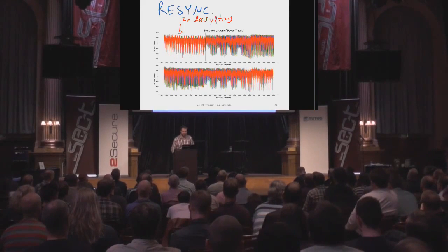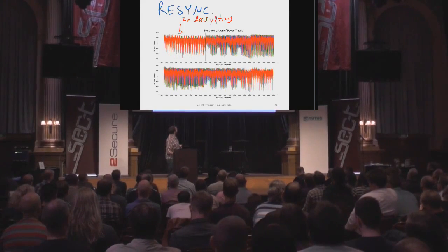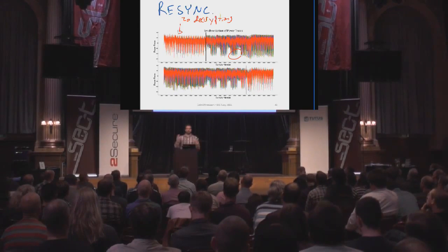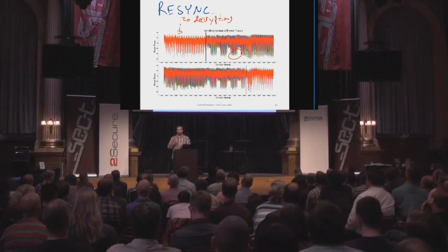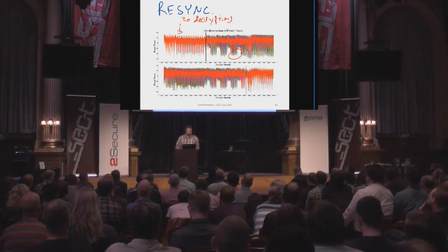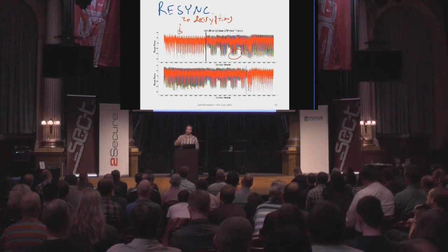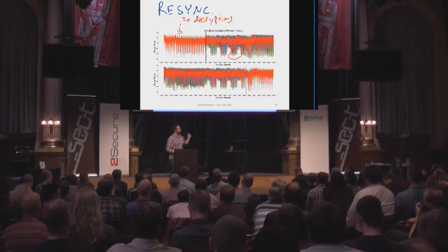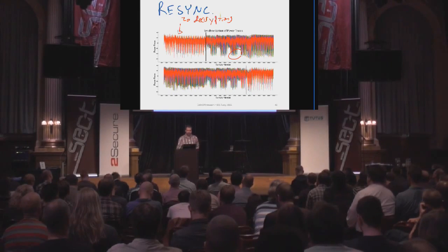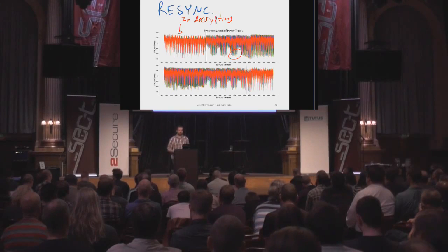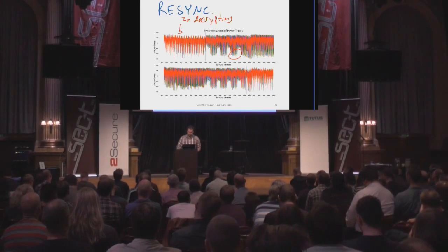What you see is that it looks very nice and aligned. At some point, it looks really messy, so they're no longer lining up. All that happens is stuff becomes desynchronized. There's some random delay when it's going through the loop. In this case, they have a timing attack in their AES, but it could be you have an interrupt. If it's running with an OS, it may have an interrupt partway through the encryption, so you've got to resynchronize stuff. That's very easy to do in software. It just shifts it all based on a pattern. This type of stuff is well known in image processing and video processing. It's not remotely new or difficult.